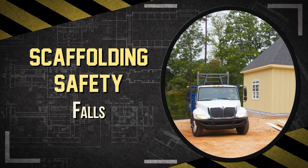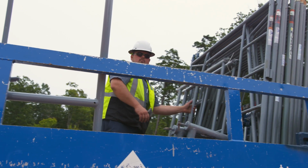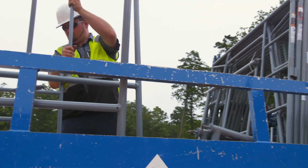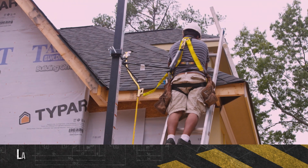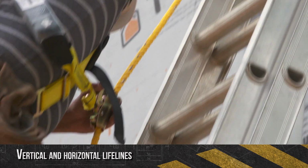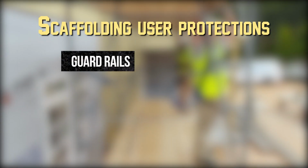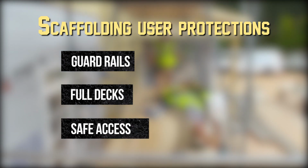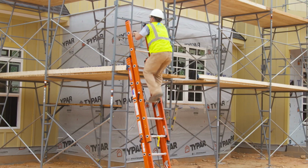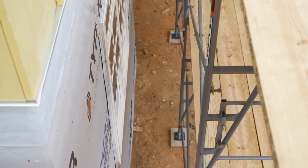There are requirements specific to scaffold erectors and to scaffold users. Erectors have to use a combination of fall protection methods, which include body harness, lanyards, and vertical and horizontal lifelines. Users must be protected against falls by guardrails, full decks, and safe access, and knowing when they would need other forms of fall protection. Any scaffold 10 feet high or higher and more than 14 inches away from a building